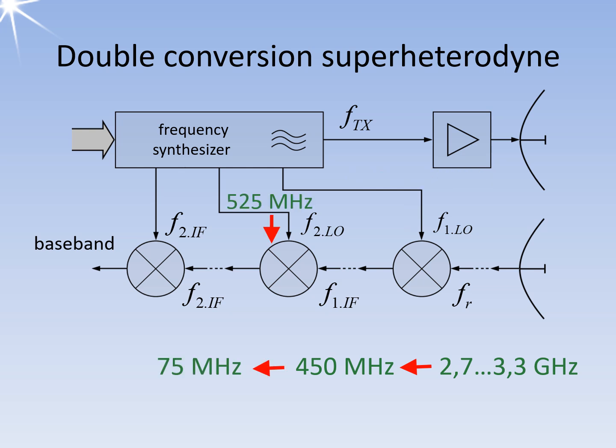The second intermediate frequency typically ranges from 30 to 75 MHz. This range is often a compromise between simplifying circuit design and ensuring the necessary IF bandwidth to process all components of the transmitted signal. The 75 MHz value mentioned here is based on a real air traffic control radar system. The second local oscillator frequency is a stable, fixed frequency at 525 MHz. The third frequency used for down conversion is the center frequency of the IF amplifier, which is exactly 75 MHz in this case.